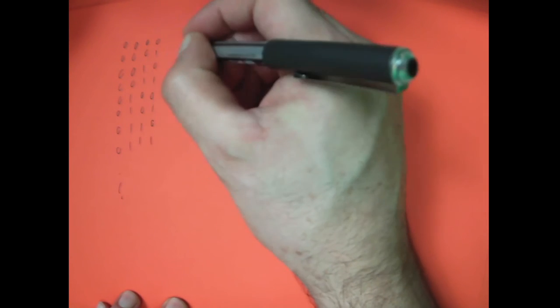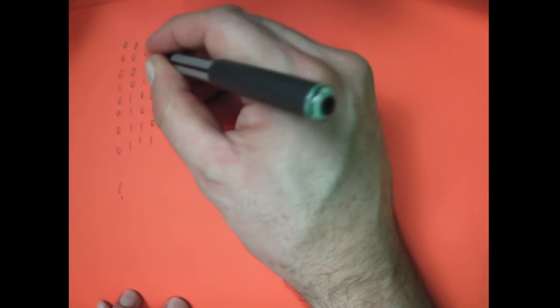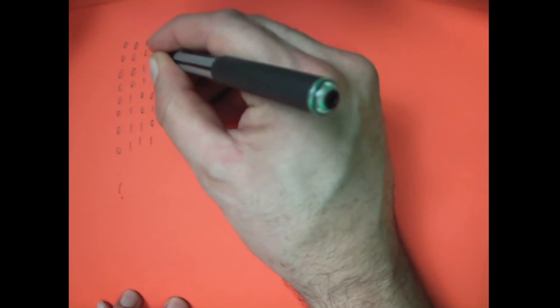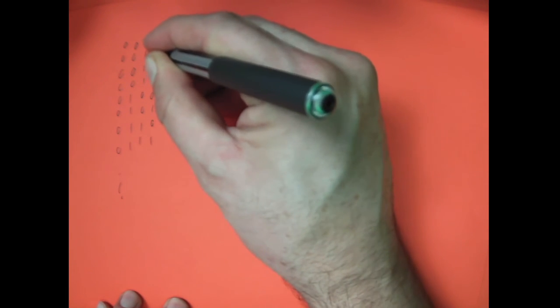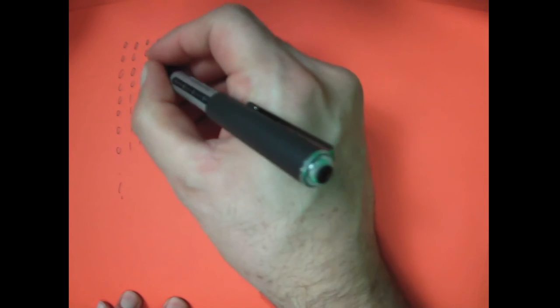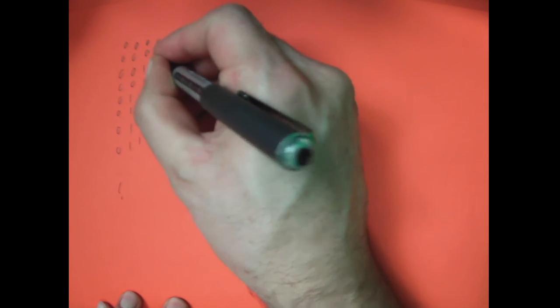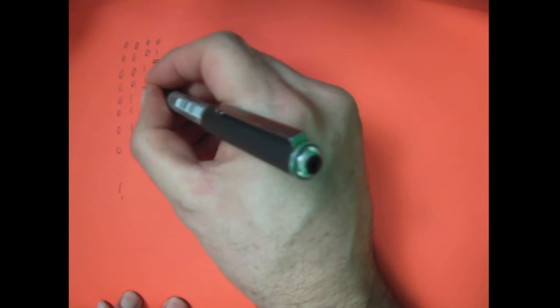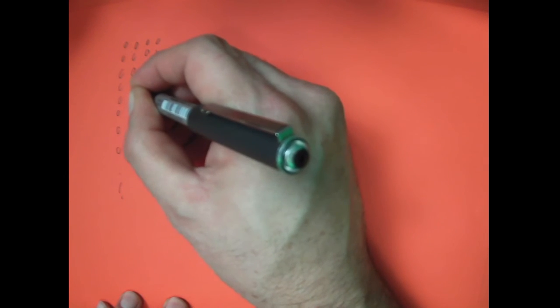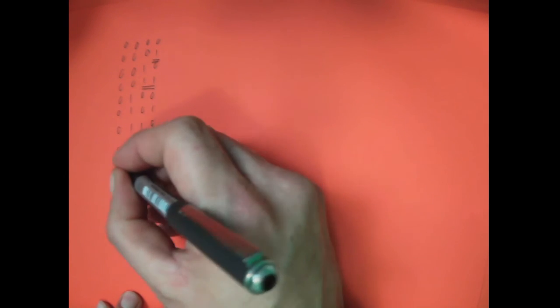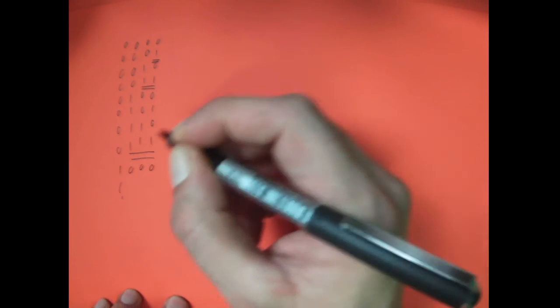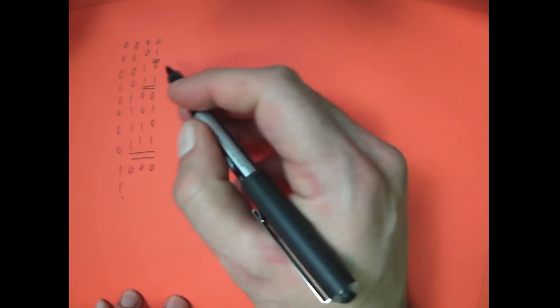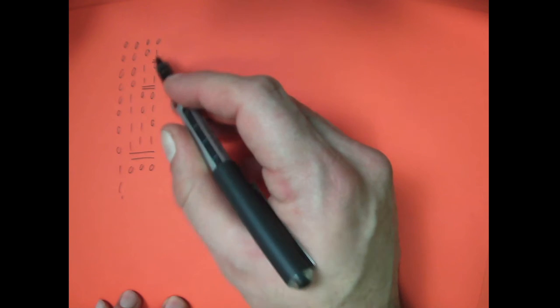If you always look at this, when the next value rises to 1, then you have the situation that the previous ones are completely filled with 1. And also here, the previous ones are completely filled, and also here. So you can use this now for your up-down counting.